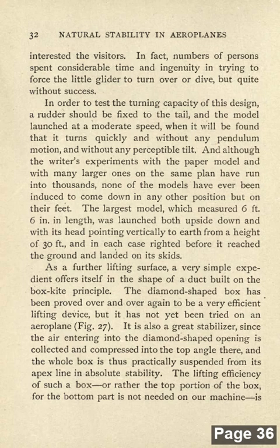A very simple expedient offers itself in the shape of a duct built on the box kite principle. A diamond-shaped box has been proved over and over again to be a very efficient lifting device, but it has not yet been tried on an aeroplane. Fig. 27. It is also a great stabilizer, since the air entering the diamond-shaped opening is collected and compressed into the top angle there, and the whole box is thus practically suspended from its apex line in absolute stability.